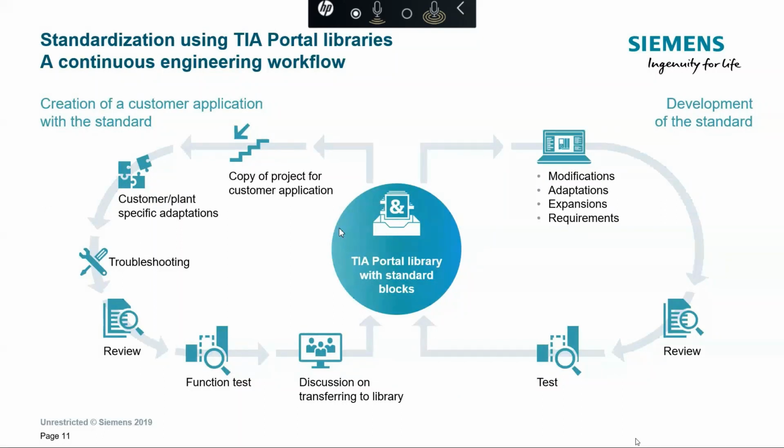So this kind of process, once you do it, and later on, in a very new project, once I am using a block from the same library, just let me tell you one aspect. Just think of the testing aspect. I mean, testing of that entire logic. You are pretty sure that you're using a well-proven block from your standard library, so you can just concentrate on the testing of the integration part. You need not worry about how the logic within the library block itself is working.